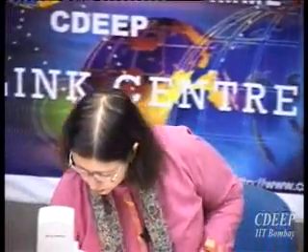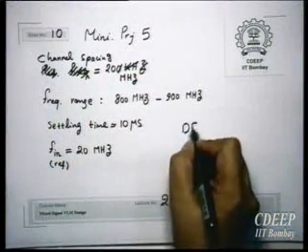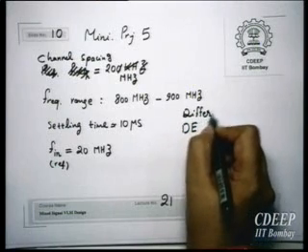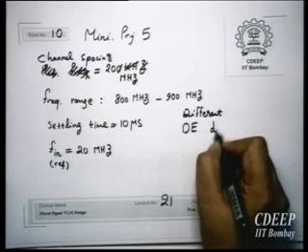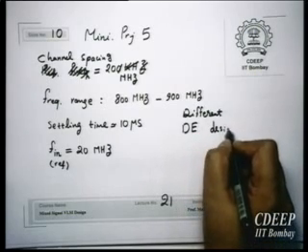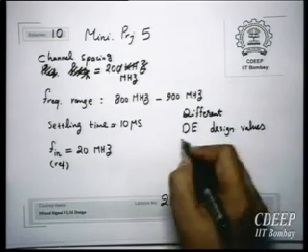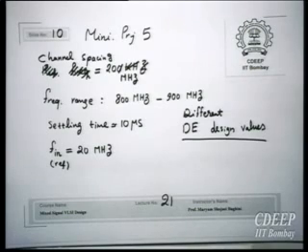So therefore, don't use the same VCO. The delay element should be different. And also don't use the same charge pump.